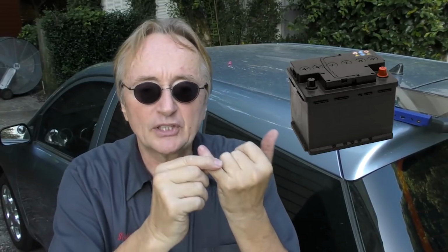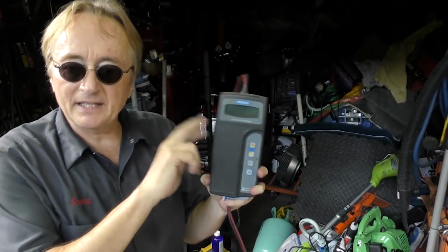Let's say you're having electrical problems. The first thing I advise all my customers to do is have the battery load tested and have the alternator load tested. Many auto parts stores do that free. You can even buy a quality thing to test it yourself these days for $70, $80. You don't have to buy an expensive one like this Midtronics. This thing was over $800 when it was new. Today, you can get $60, $70, $80 versions from other companies that work quite well.